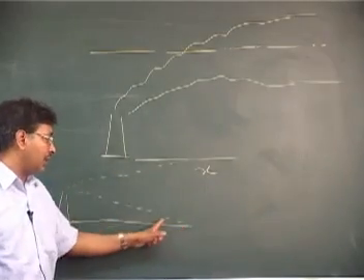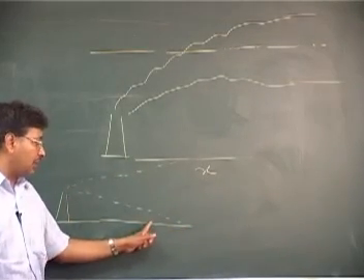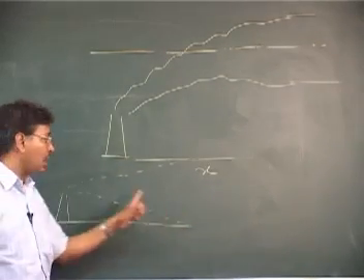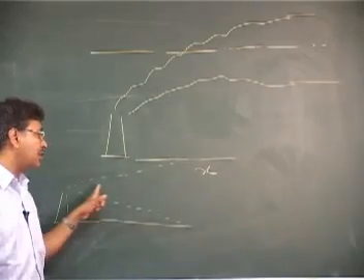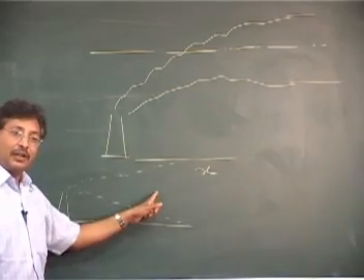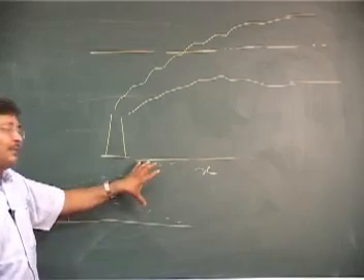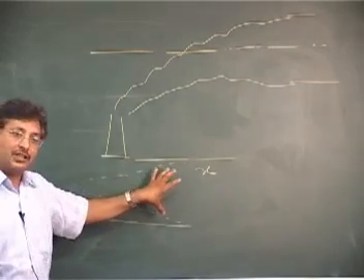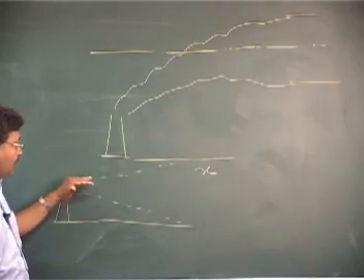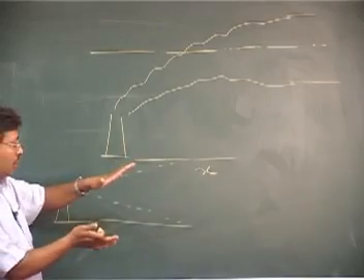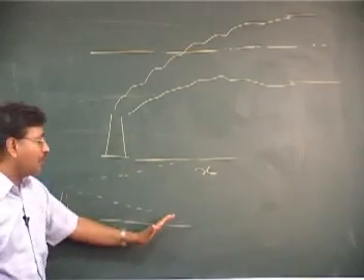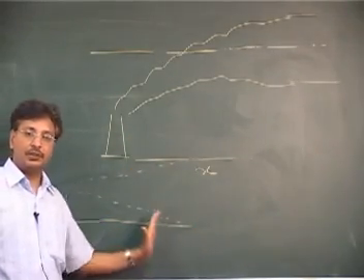At some point, you see the concentration will start increasing. Okay, and what is the plume in general? The center line of the plume is affected by the stability, or the conditions which are inside the plume. So then we see the impact of this dispersion or this expansion of the plume. What will be the impact onto the ground level? This is what we are seeing.